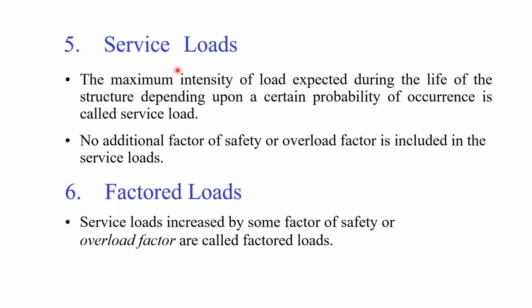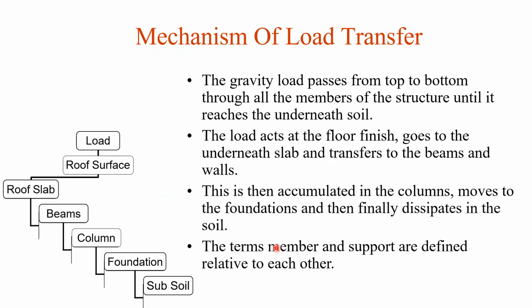Factored loads mean loads with factors, service loads increased by some factor of safety. When there are dead and live loads, you multiply 1.2 into dead plus 1.6 live, and that will be the factored load. If there is only dead load, then the factor will be 1.4 dead, as given by the code.